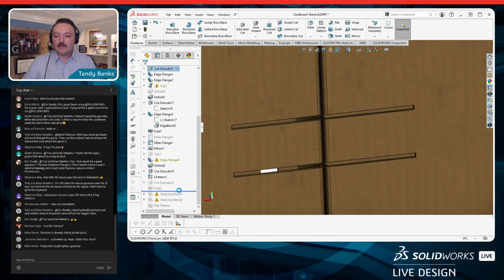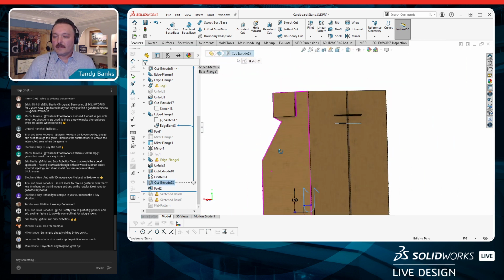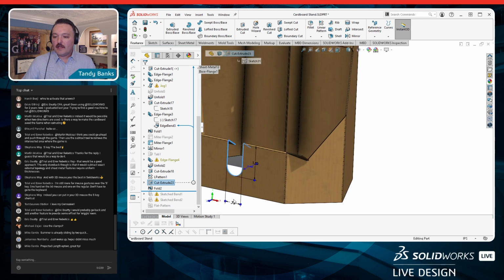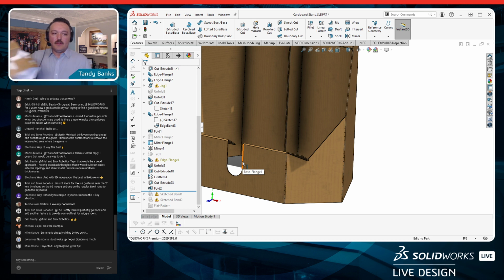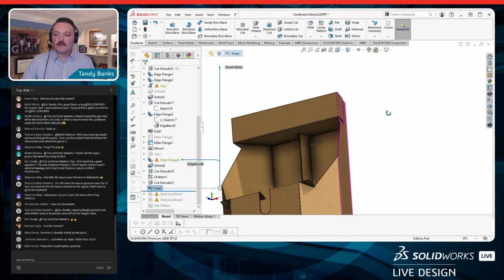And then I'll scroll back down through here a couple times, and we get to where I created one more cut up front, and this was for the cable, because it was one of the things that wasn't in the original design, but we decided real quick that the cable is the charging port, so I needed a slot for that. And so we made that cut while I was in the unfolded state, so I didn't have any geometry that was overlapping one another, and then used the fold tool once again in order to fold those up.